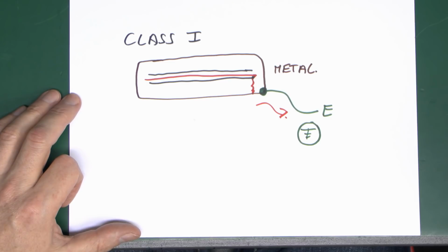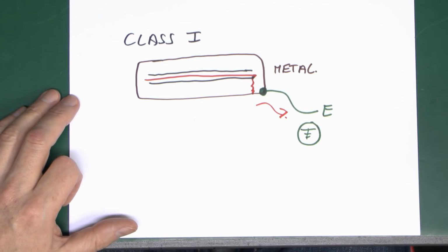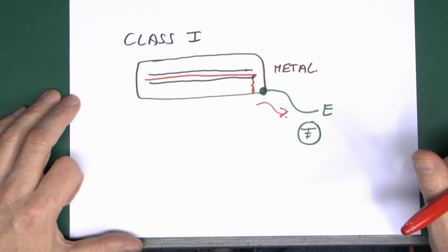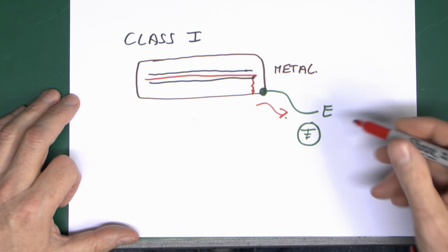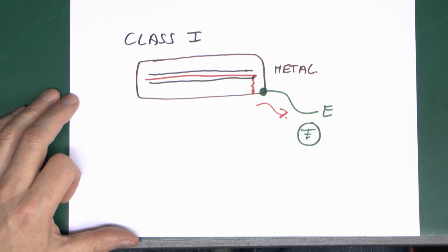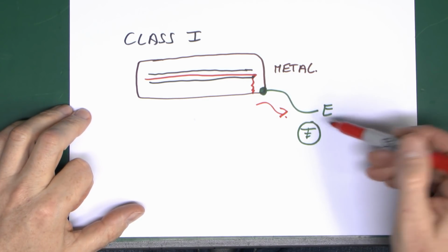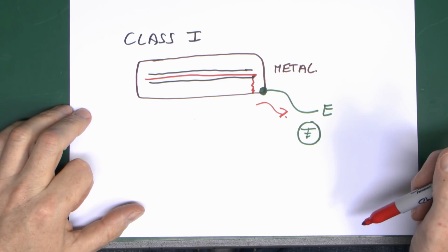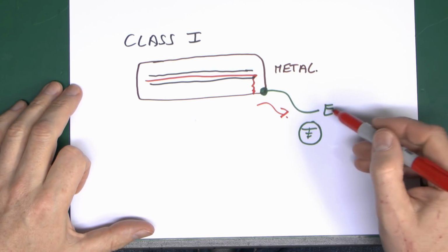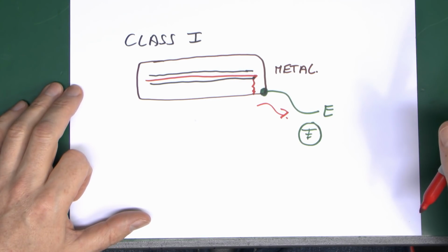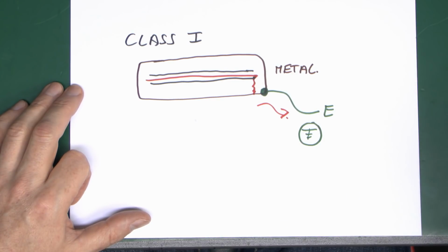So that's a very common item, particularly on things like kitchen appliances, washing machines, ovens, cookers, electric kettles. That's mainly because most of those things have large metal cases around the outside, which of course are connected to the earthing of the installation. So if we've got a class 1 item, it will most definitely have that connection there, and it is absolutely essential that it is connected to the earthing of the installation, and also confirm that the socket or attachment to the installation wiring is actually connected to that. And of course you need to test that when installing the equipment.